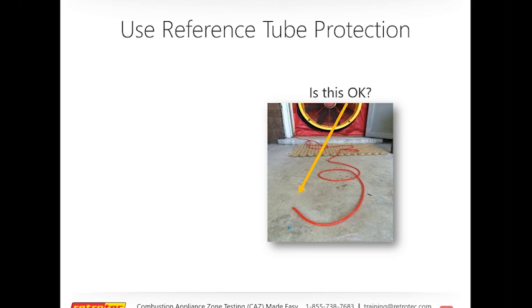Especially if you are still using a test process that uses a combustion depressurization limit. Some of the QCI folks, or even, I believe, RESNET, even NFPA, some of the older ones especially, still point to a limit of depressurization for that combustion safety zone, and oftentimes that limit is right around 5 to, say, 10 pascals. That is such a small amount of pressure.